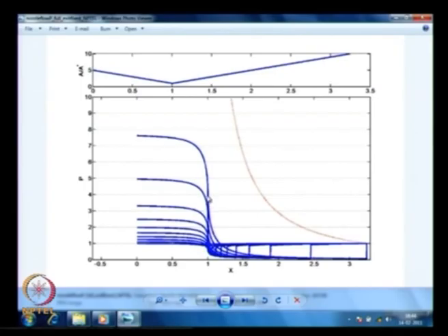If I do this particular experiment of keeping my back pressure fixed, not exit pressure, back pressure fixed, and I increase my P naught on this side, then it will decrease my P star for a little bit and then it will keep on increasing my P star, because my P naught is increasing.